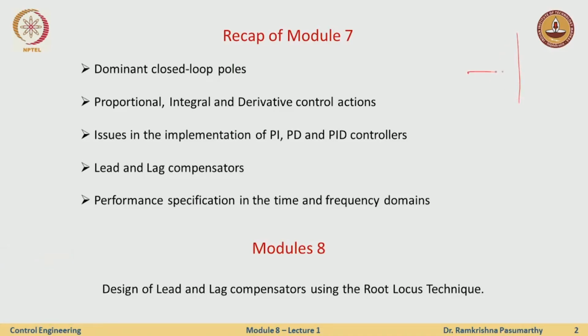So if I take a system which has poles here, here, here, and so on, the pair of poles which decide how my system behaves can be approximated by just looking at these 2 poles, because these transients die out pretty quickly. We are looking at something like exponential of some number k times t. The bigger the k, the faster they decay. The smaller the k, the slower they decay. So this corresponds to smaller k. And if they are on the imaginary axis, then they never decay. It's a constant oscillation process.